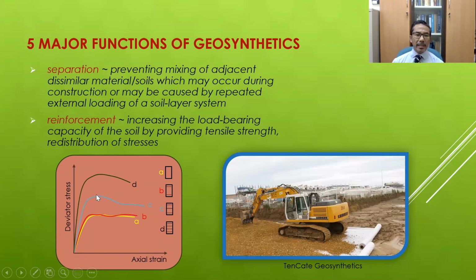So the increase in stress or strength here is due to the additional reinforcement element in the middle here, which provides what we call internal confinement. This internal confinement tends to increase the strength of the soil.